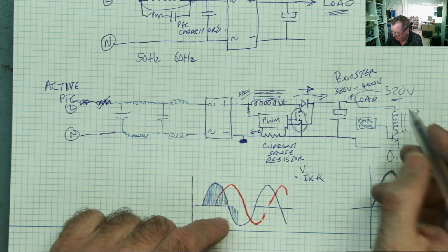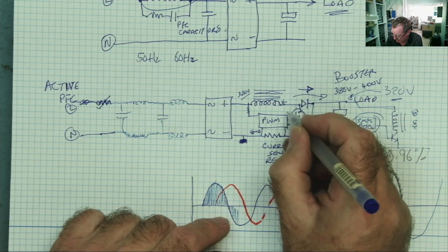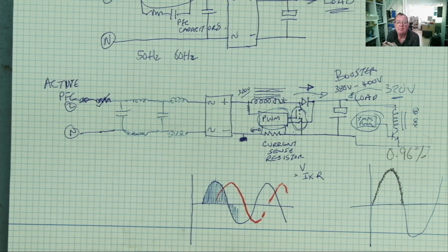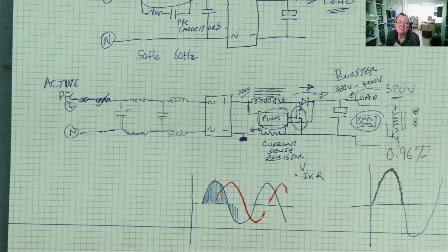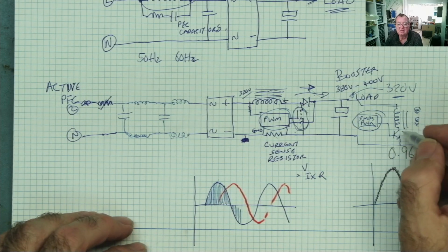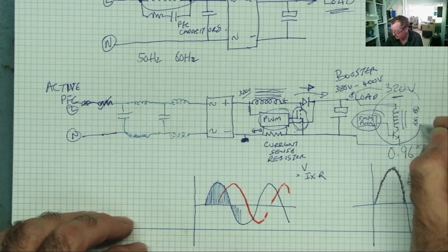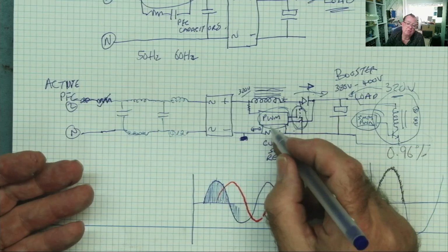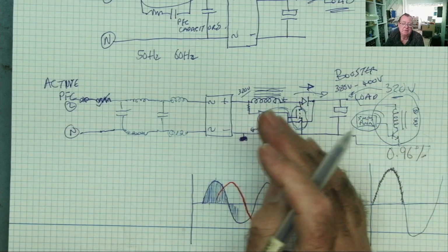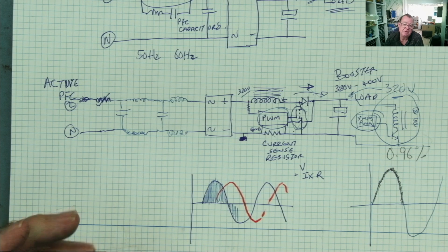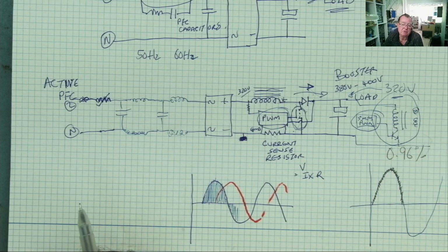You will sometimes find that that chip and this chip are both the same chip. It's a combined pulse width modulator and PFC controller all in one. In this instance, a fault in this part of the circuit can damage or destroy the chip. So this also doesn't work. So that's another issue you need to consider when you're working on power supplies that are faulty. They have PWM and switch mode power supply.